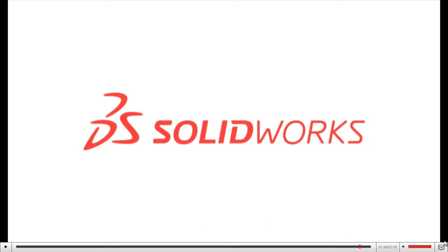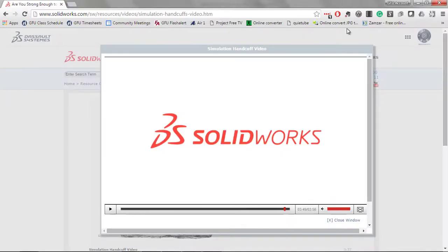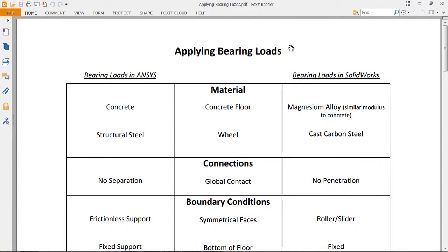Not necessarily making this a big ad for SolidWorks, but I did like the focus they had on their video. So, the big thing I want you to think about as you move forward with simulation is that when we're developing a part, we can think about how we will actually test it in the physical case, and we can try to set up the same case in the simulation. One big piece there is figuring out how to apply the load on the handcuffs, which is a little difficult, and I've seen this before, especially when applying loads to the top of bolt heads.